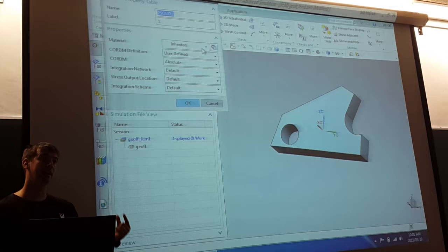We can look at subcase constraints, a linear static analysis of subcase constraints. What that does is it makes a set of subcases where in each subcase you are applying different loading conditions or constraints. Right? So you can skip through those different cases to look at the analysis from different sets of analyses for those conditions.